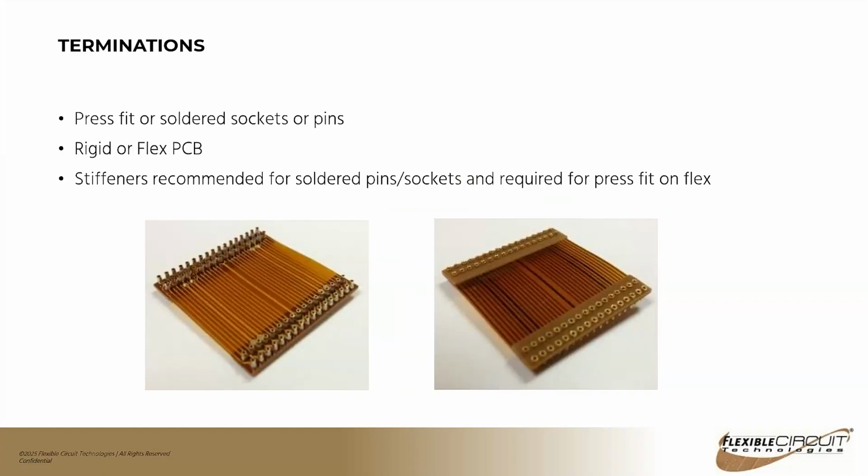And then press fit or soldered sockets or pins. Stiffeners would be recommended for soldered pins, and then they're actually required for press fit because you're not going to want to press fit a pin or a socket into a circuit. You're going to deform your plated through hole and damage it and possibly crack the plating.